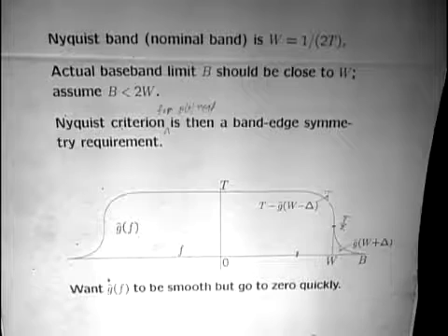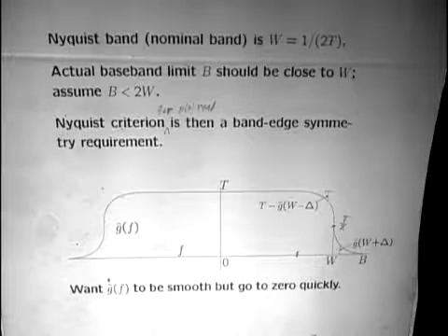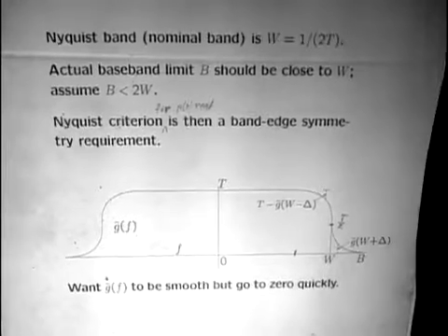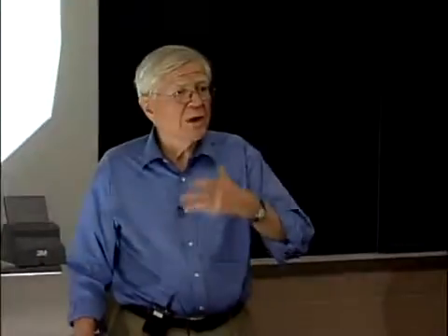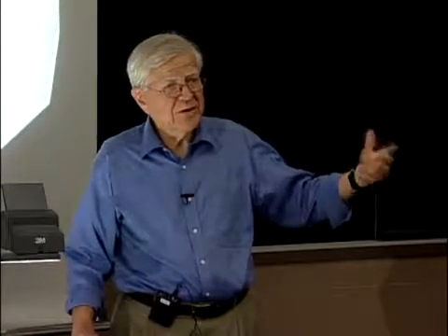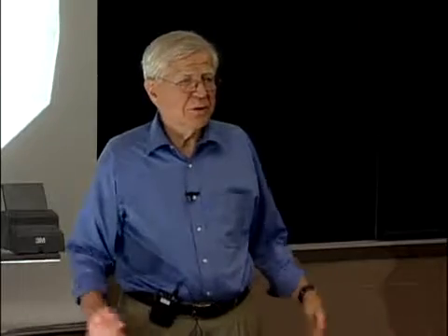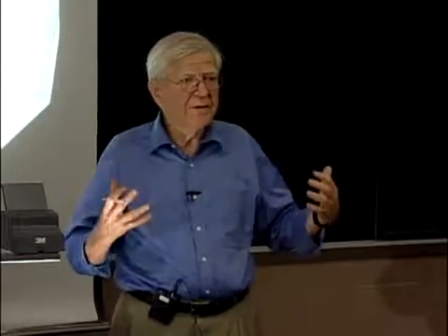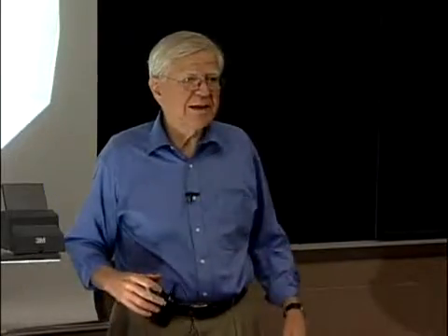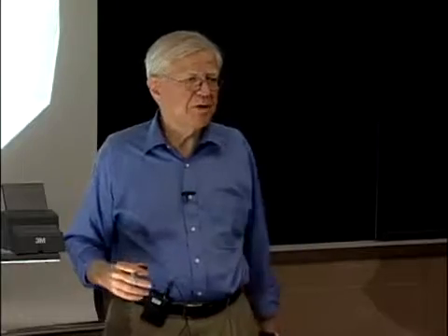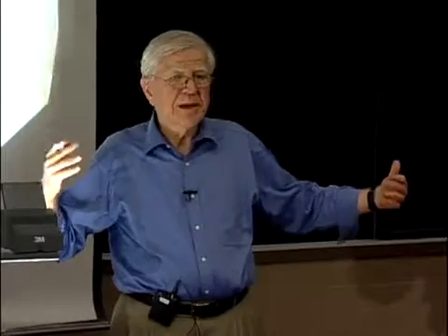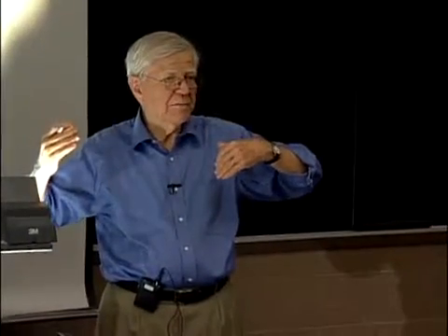Okay, in other words, the point here is when we're doing transmission of data, we know what the data is, we know what the filter is, and we can use aliasing to our advantage. When we were talking about data compression, aliasing just hurt us because we were trying to represent this waveform that we didn't have any control over, and the out-of-band parts added into the baseband parts, and they clobbered us because we couldn't get the whole thing back again. Here we're doing it the other way.